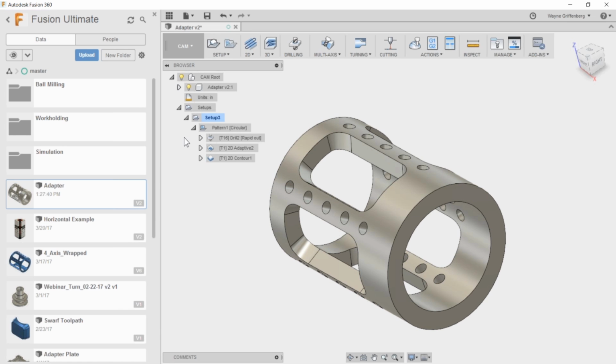Toolpaths to it, you can right click and import new version. So if the Inventor file changed and has some new features added to it, you can import that new version into Fusion. It'll come in as the latest body. You won't have the features, but it'll come in with the updates. Now, once you do that, it will not retain the CAM on the part. The CAM will go away because the CAM is no longer on the part.